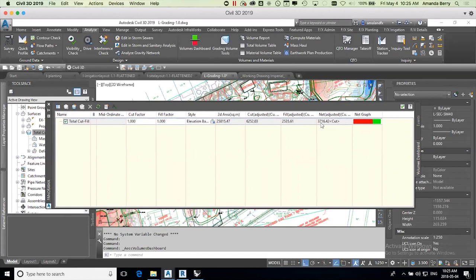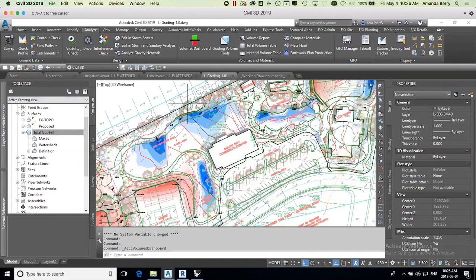You can adjust how this works in terms of if you go to subgrade, you can incorporate a lot of different surfaces all together with different subgrades and calculate the entire cut and fill. You can take it basically as far as you want, and I found it so incredibly accurate. I've had soccer fields, say, like parks just like this, where the contractor has come back to me after building the whole thing and told me that, oh, hey, your cut and fill calculations were wrong.